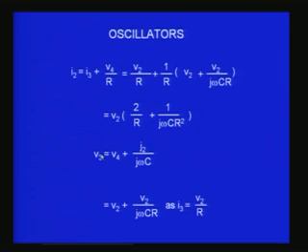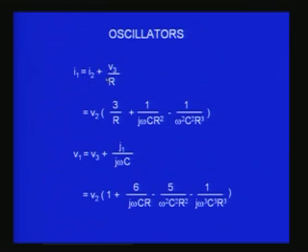So now V3 is, I have to multiply this by the corresponding number, V4 plus I2 into the 1 by j omega c. So you substitute for that again from the earlier expression for V4, and you will get this expression. And similarly you go for one more stage, I1 is I2 plus V3 by R, and you substitute, you get this big expression, and finally you can write V1 in terms of V2.